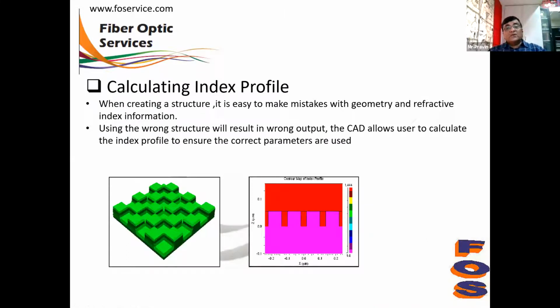RSoft CAD allows the calculation of index before you actually do the simulation, because if you have a certain structure in mind, and if there is a mistake in drawing the structure, all the simulation results will be very wrong. So before actually simulating this structure, you can see the index profile of the designed structure, whether the index profile is correct and what it was intended for.